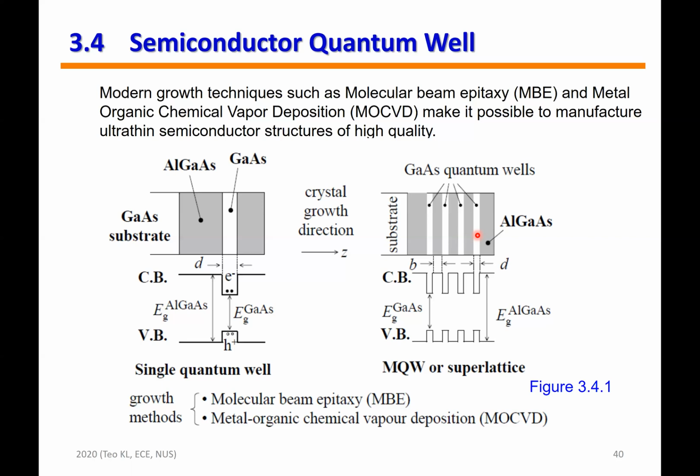Some of these growth methods, as I mentioned, can be done by molecular beam epitaxy or chemical vapor deposition. Most of these deposition methods, such as MBE in this case, or MOCVD, or even sputtering, as we mentioned previously, are typically far from equilibrium conditions, which means they are grown in a metastable state, without spinodal decomposition.